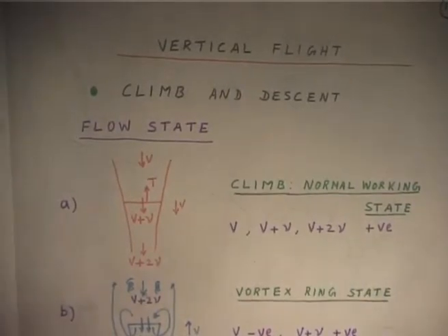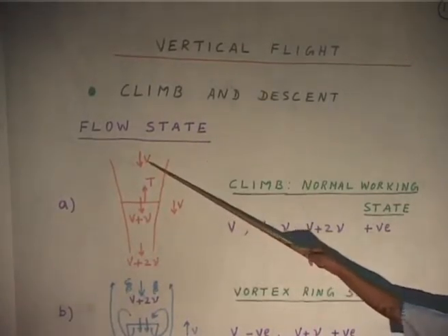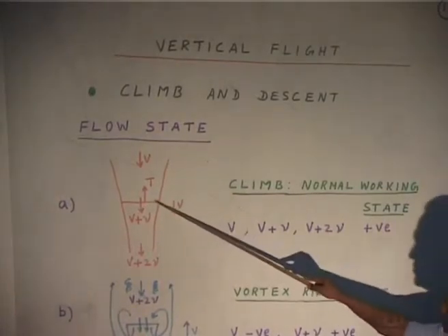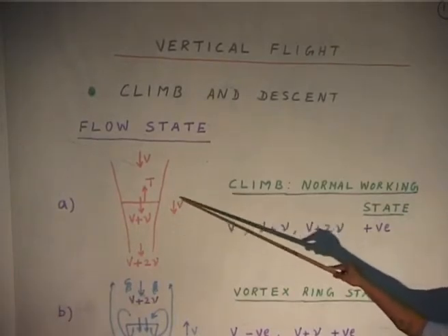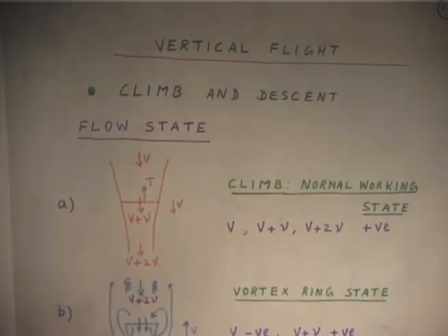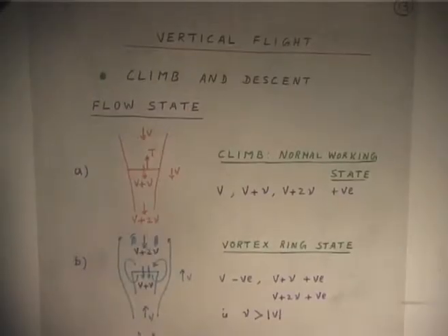If you are sitting on the rotor, what you will feel is the far field upstream. You will see the wind is coming with the velocity V, and everywhere, because you are moving, the wind is going down. This is outside the slipstream, velocity is also down, but the rotor is doing some work, and that is basically increasing your velocity. We will derive for this case also.